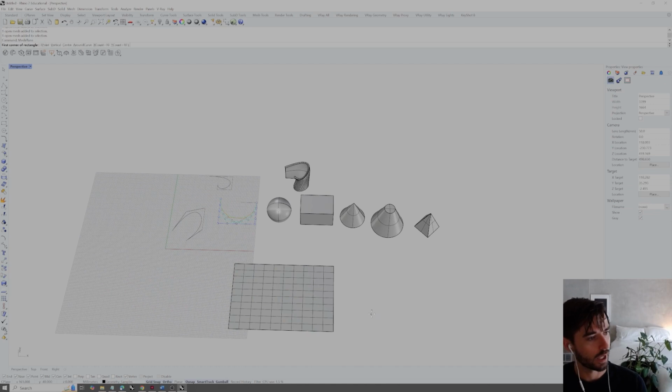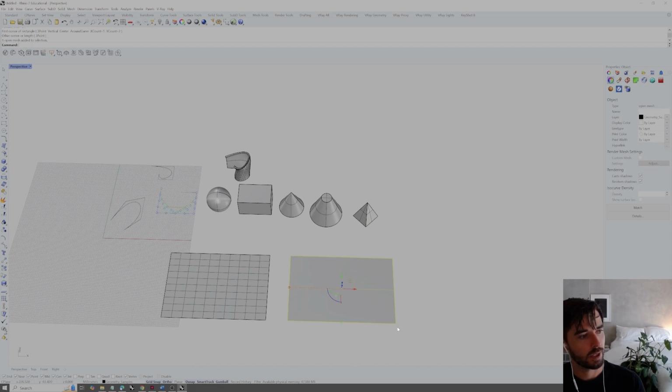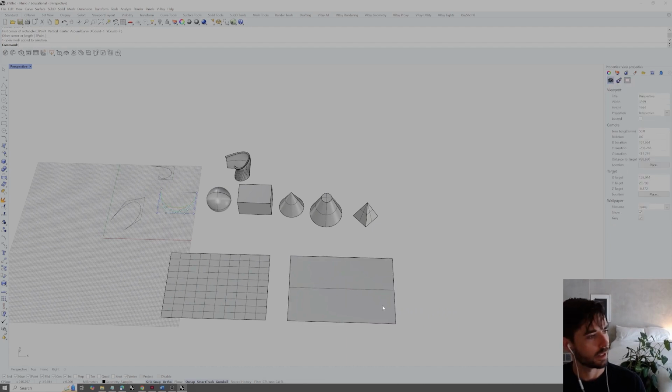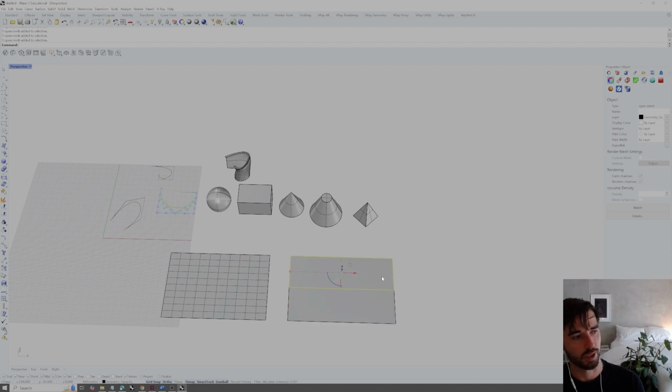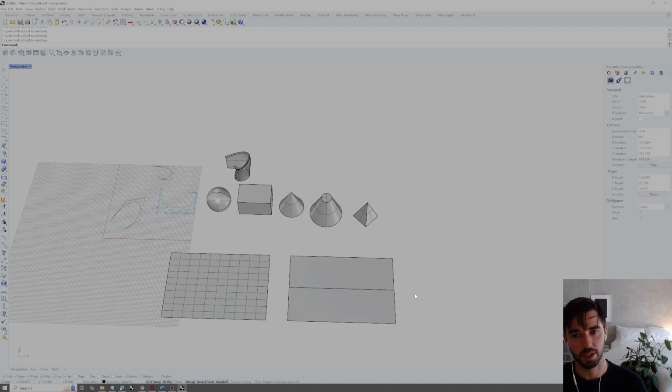If we were to draw another one, so type again, mesh plane, and change that X count to 1 and Y count to 2, let's say, and then draw another plane, we now just have one face in the X-axis and 2 faces in the Y-axis. If we wanted to separate these, we could type extract mesh faces, select a face, enter, and we now have the mesh exploded into 2 separate meshes based on their faces.